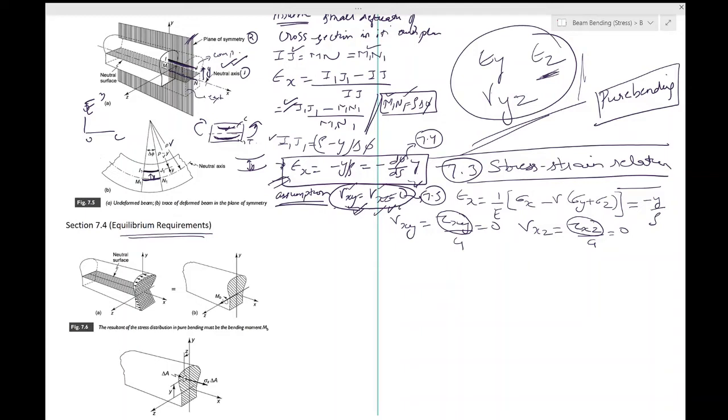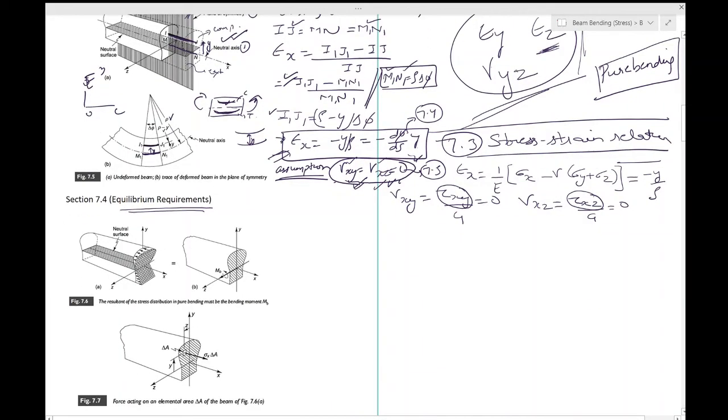So the stresses which we are finding must be such that their resultant is the shear force V and the bending moment MB, and that relation we will achieve through the following equilibrium equation. And this is the third step. In 2.1 it's the first step, but it's the last remaining step.